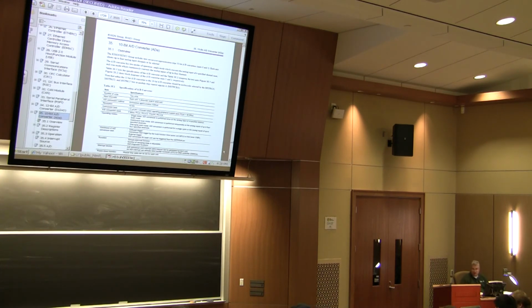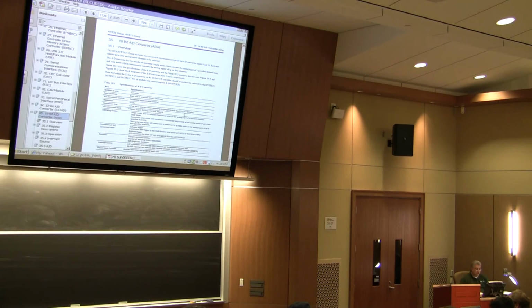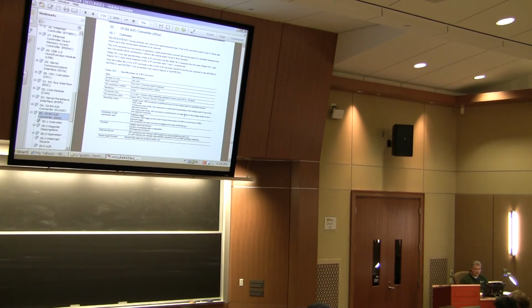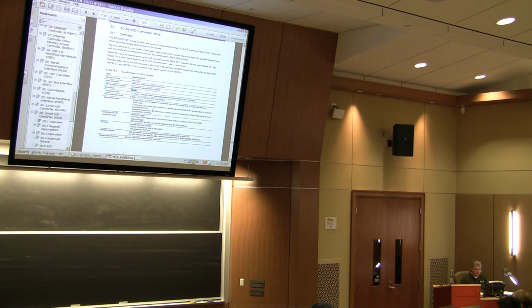So, if I were to ask you some questions about how to do an analog to digital conversion by first, as I said, initializing your control registers and then actually doing some measurements, you would go to this section and it would give you some ideas of how you could do it. So here, successive approximation method, what we covered in class. There are 2 units, interesting. Each unit has 4 channels. There is 10-bit resolution for this particular unit. Then this tells you how it operates. Single mode: A to D conversion is performed once on the analog input of a specified channel. This is often what we call one-shot. Or you can continuously scan up to 4 specified channels. Software trigger, external trigger functions.